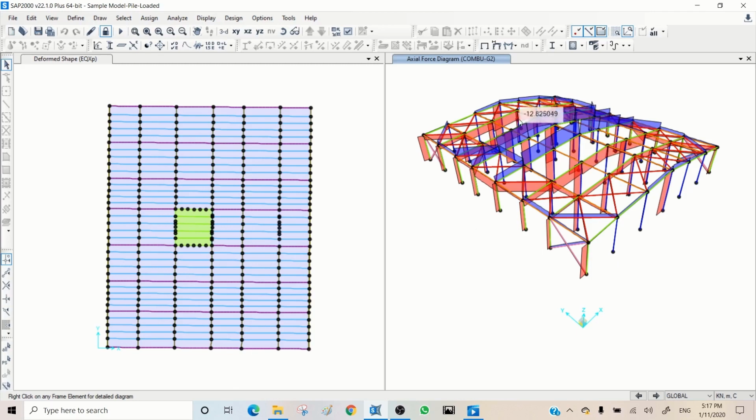And you can see some things here. For example, in axial force, there is no axial force here, so it could be a mistake in the model, or it could be because of transferring load to somewhere else. You can see the same here, it's not going to the end, so it's actually coming to the brace. But the middle ones are different because they are not braced. So when they are braced, the bracings are participating.